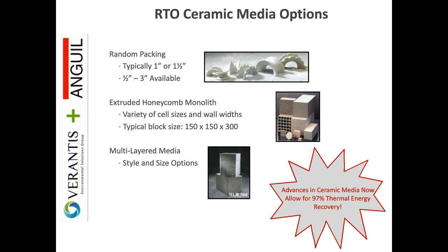The key thing to remember here is if the RTO is designed properly and the media is chosen properly, these will all do the same thing in that they will all be able to achieve 95% on the low end thermal efficiency. Now the key here is with some of the newer structured medias, we can actually achieve even higher, 97% thermal efficiency.